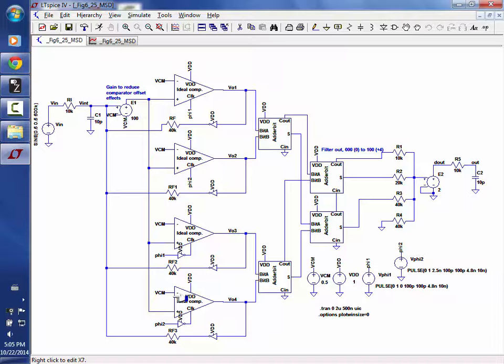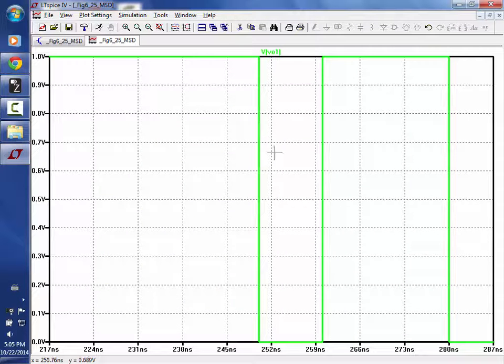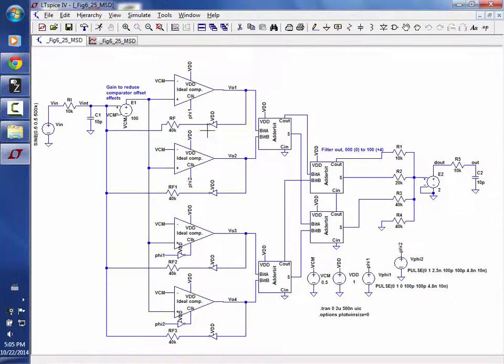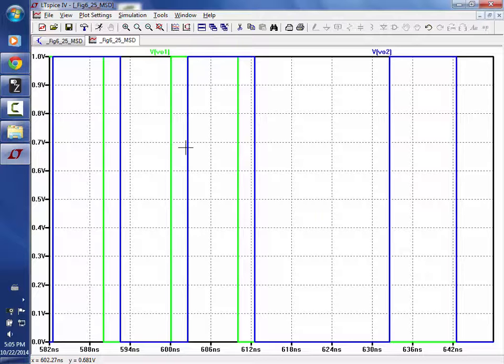That's the point. You want those forward paths to operate slow. You want them combined and feeding back to have a very high sampling frequency. So this path of this comparator doesn't have to operate at 400 megahertz. Does everybody follow that? So if I go back and I look, that's not very interesting. Oh, because I'm zoomed out. If I go back and I look at the width here, this width is 10 nanoseconds. If I go look at the next one, and I look, it's 10 nanoseconds too, but it's shifted by 2.5 nano.